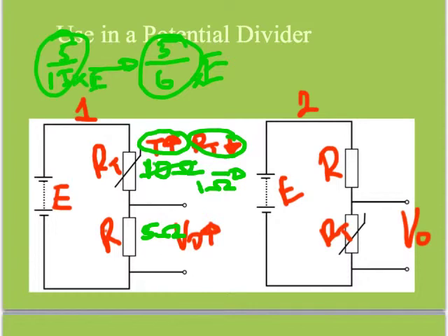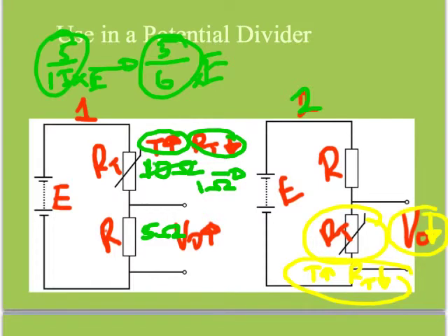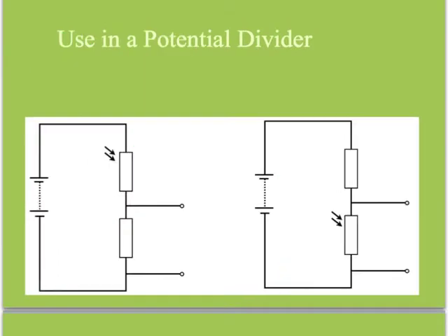However, circuit number 2 is actually opposite, because the resistor is now down there. So if the temperature increased and the resistance then decreases, that output voltage will actually decrease. So you need to explain all this in words, essentially just like I did with these diagrams, but in a longer way. And the same thing happens with the LDR.